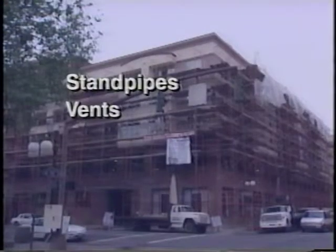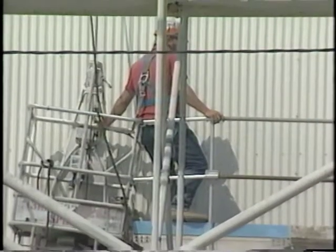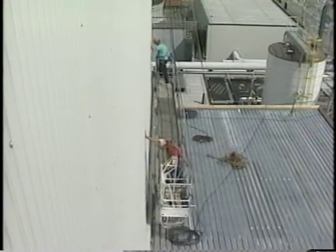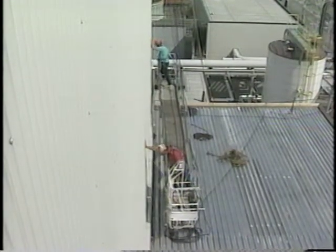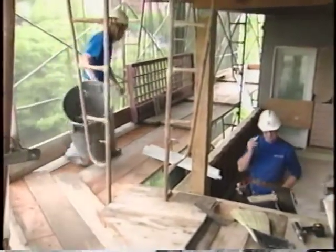Standpipes, vents, drain pipes, and electrical conduits on buildings are usually not considered proper anchor points. If structural members of the scaffold are used as anchor points, the scaffold must be tied or have independent support lines. Falls can also be prevented through safe work practices.